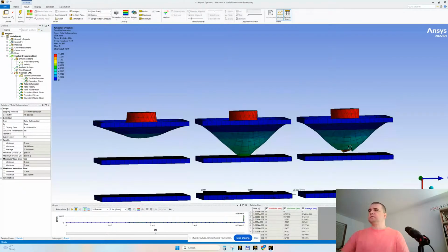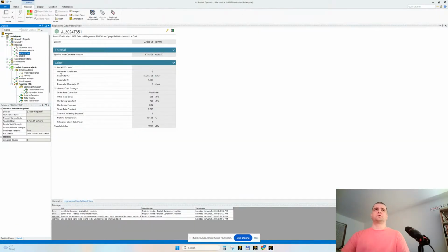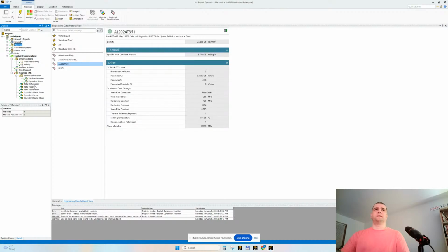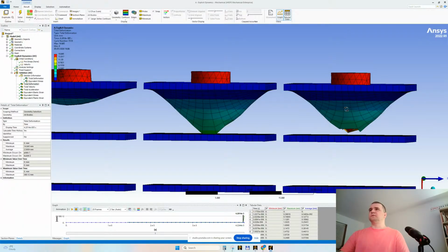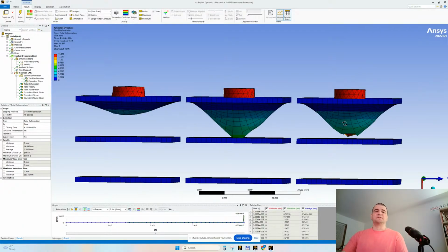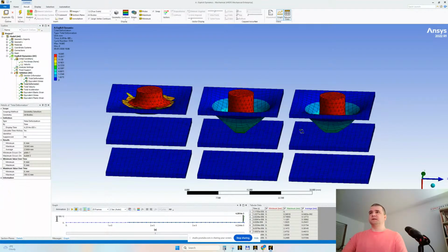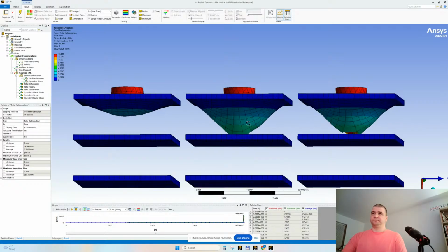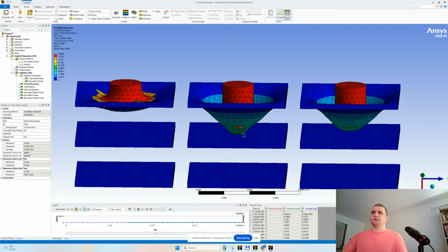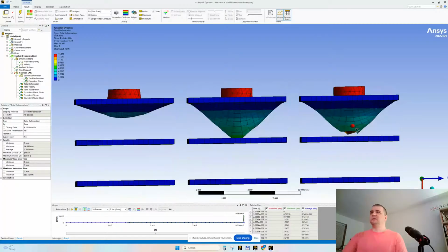Bilinear isotropic elasticity, and this is with, I don't know, Johnson-Cook or something. Let's see. Johnson-Cook, yes. So we begin to see fracture, yes, because we used properly defined material for such a load, for such a quick time event, yes, in explicit dynamics. Also, what we can see, we need to refine the mesh. Look here, yes, the elements are going to be too big,